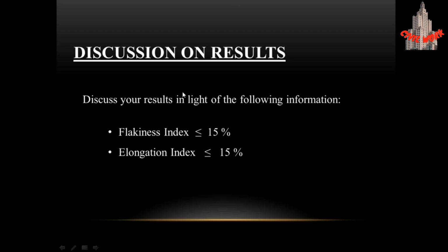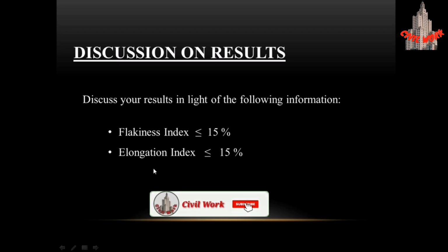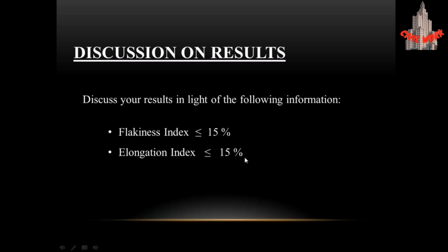If the flakiness index is less than or equal to 15%, it will be fine, and the sample would have a greater strength. And if the flakiness index or elongation index is greater than these results, then the sample would be discarded and not used in our construction.